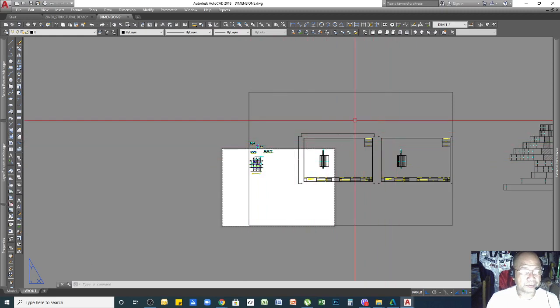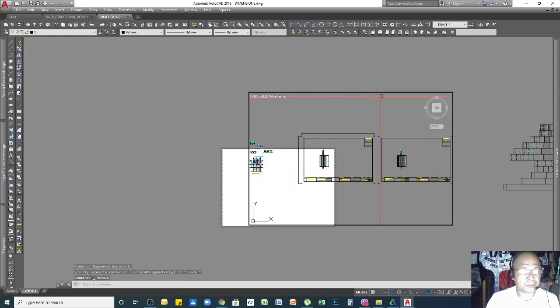What you will do is double click your mouse inside the multi-view area like this one. As you notice, my mouse is now inside that box. So technically I need to set the drawing content inside this box only. Outside of this box will be considered out of the picture, or if I print, I will limit it to this box. Those outside the box will not be included during the printout.